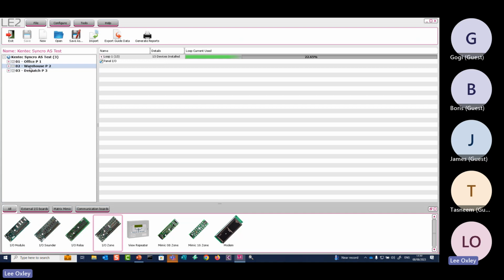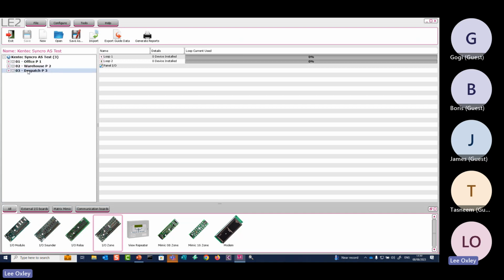Walk over to panel 2 and do exactly the same there. Then walk over to panel 3 and do exactly the same there. Upload all panels this config file. Let the panels come back, turn back the right enable switch, do a reset, and now you've just added a panel to the network. It's as simple as that.